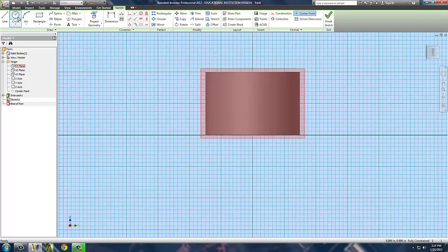Now, what does this do for us? It allows us to do things like if I want to cut or make a shape right there that comes through this, I can sketch it in. I can say, okay, I want to know that it's exactly ½ an inch from the top and ½ an inch from the bottom of this part right here. By controlling that, those are location dimensions, a ½ inch from top, ½ inch from bottom. I did not control the size. The size is dictated. Now if I want to, I can actually control the size here as well. It's trying to do it as an angle, so I'm just going to leave that be for right now.